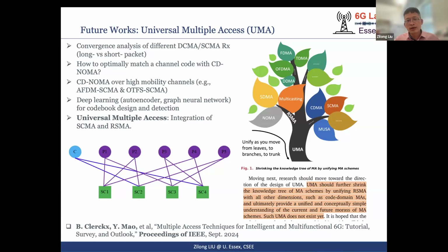Here we can see some very unique linkage. For this 4x6 SCMA structure, if we are able to use one layer or even two layers to send our common message, then we are able to see some new insights. For us to carry out this kind of message splitting, we will need to consider the unique structure of SCMA to carry out the rate analysis, such that we are able to match the specific modulation order as well as the channel code. Overall, I can see such a direction is still missing, so I would highly encourage us to look into it.